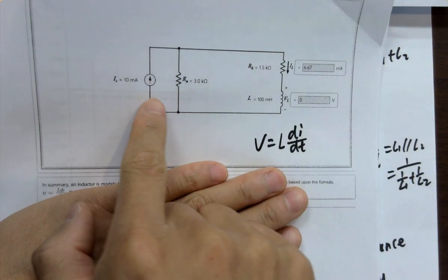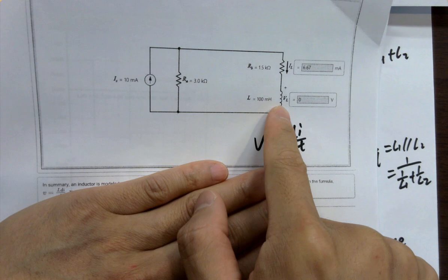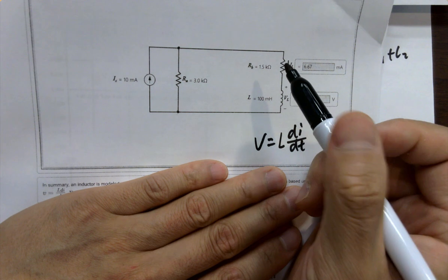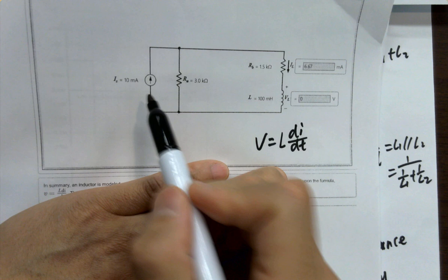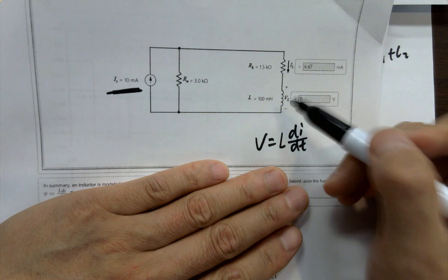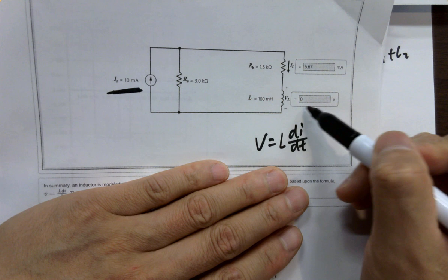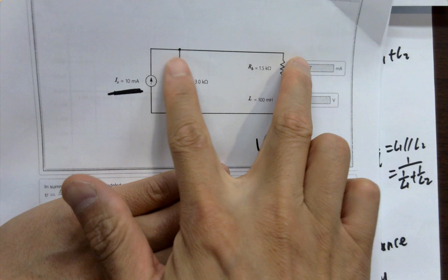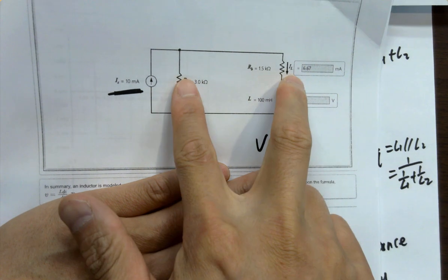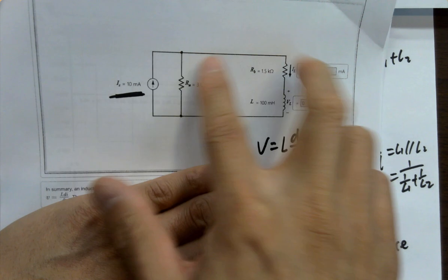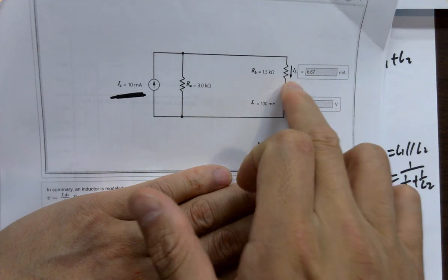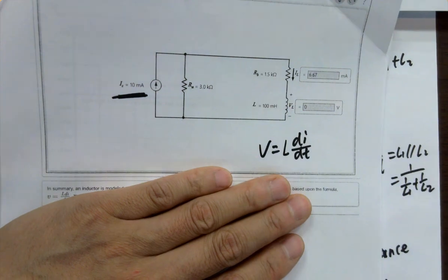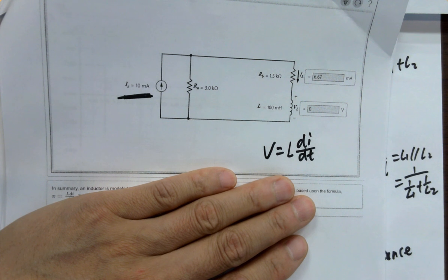So this question is asking you to calculate the current that flows through this guy. After turning it on for a while, whenever it's settled and not changing anymore, it's DC. How to calculate the current through it? I know it's asking for voltage, but also for current. It's a current divider. You have two resistors, and this is ignored because it's a wire. Two resistors and one main current, so you can definitely calculate the current in here. Current calculated. What's the voltage though? I told you it's a wire. 0.